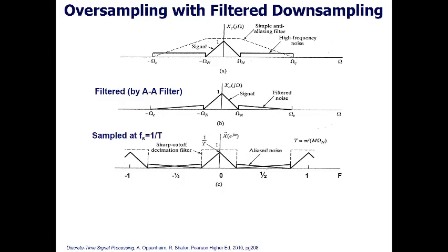And in some cases, we can get away without quite as high a sampling rate as we might have needed if we're okay with some of the noise part of the spectrum aliasing, overlapping. We don't want that signal anyway. And what we'll do is take that next stage. So we have our discrete time signal with all its spectral copies and some aliasing going on, but aliasing only going on in the range of frequencies that we don't care about, the noise part. We don't let any aliasing happen in the original span of frequencies we wanted to keep.